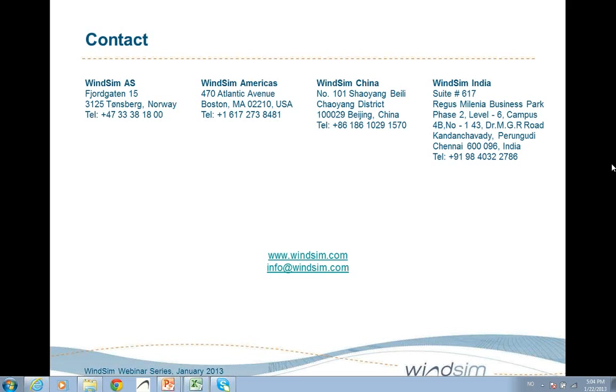Then we have a question about, usually we get 1 meter resolution inside the target terrain and have to use SRTM for surroundings. How does this affect WindSim results? This depends a bit on how large your target terrain extends over the pure turbine area.